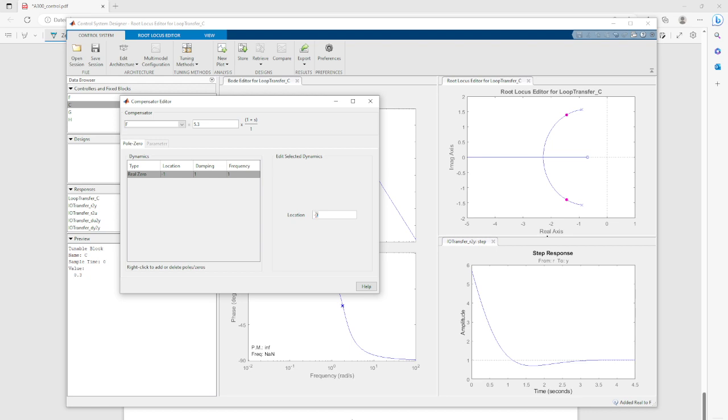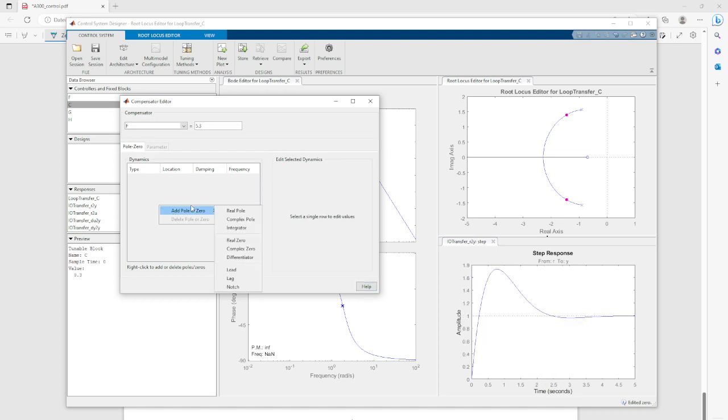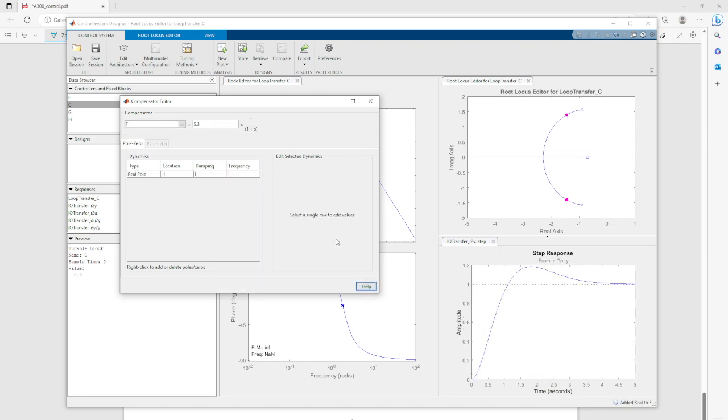Actually, you can put in minus 0.7 here. And now Matlab immediately does something. Sorry, not a 0, my mistake. We want to compensate the 0, obviously, with a pole. And we want to place that pole at 0.7 in our pre-filter. And now we actually have a nice response, right? Now we actually have compensated that 0 here in the pre-filter.